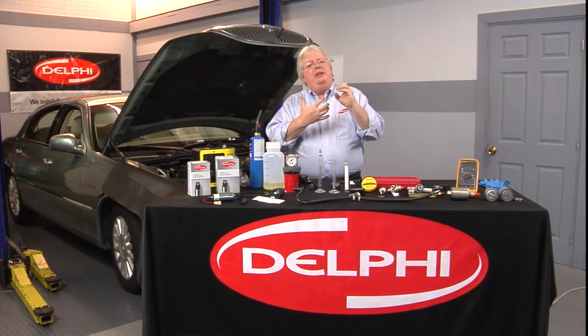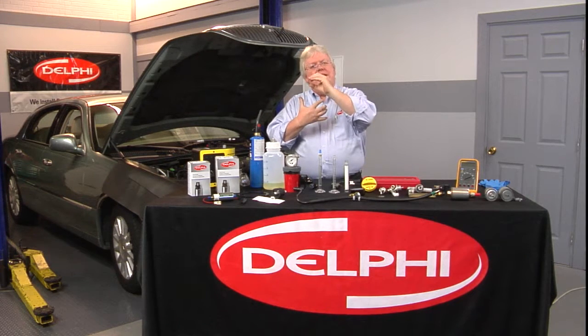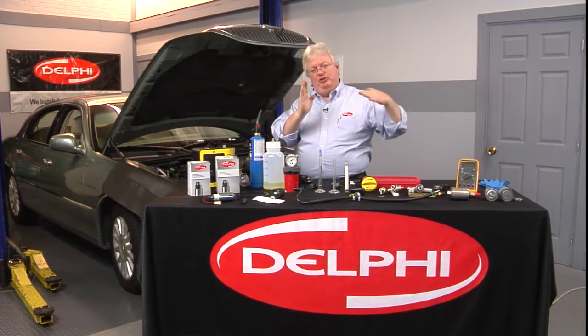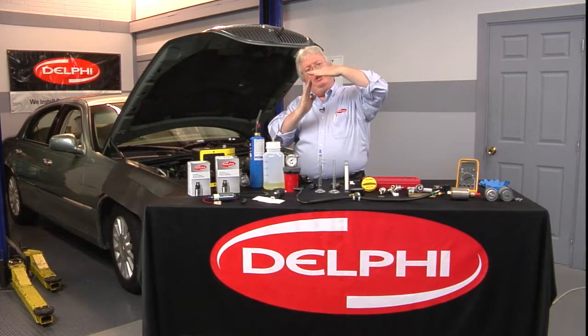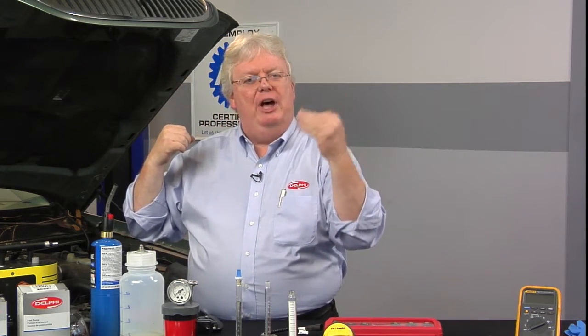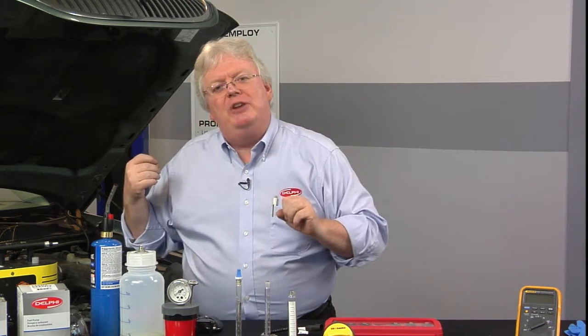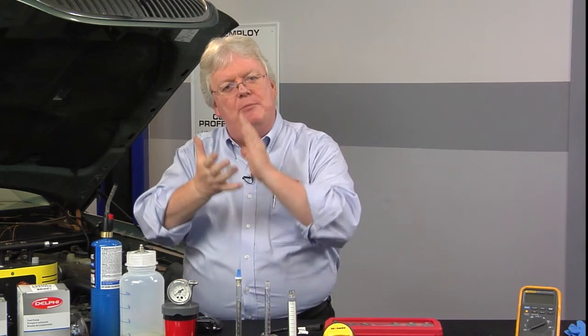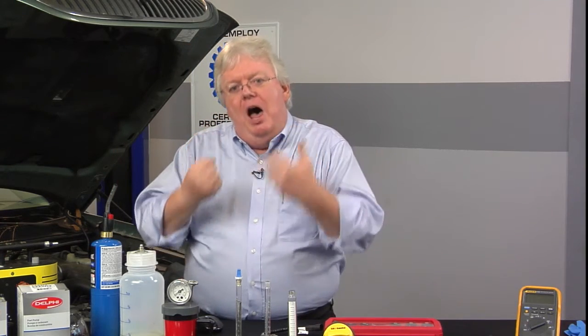That particular position where that block of memory is will be when we cross the line of so many RPMs and so much engine load, and the computer saw the short-term fuel trim kept maybe hanging low or going higher than 0. We watched it over a course of time and made a correction, a permanent or semi-permanent correction in long-term fuel trim, which is stored in memory. So these blocks of memory are what we clear out when we do a fuel trim reset. It's what the computer programs in and keeps in non-volatile memory. In other words, the key cycle doesn't affect it.